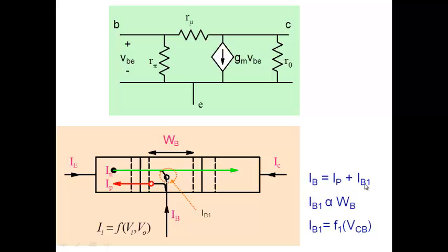So now there is a component of base current which depends on recombination. Where is the recombination occurring? It's occurring in this region that you see here, this base region. So obviously you can imagine the electron is coming here and it is traveling over here. If the base is very large, there's more chance of an electron undergoing recombination. If the base is very thin, there's less chance of electrons undergoing recombination.